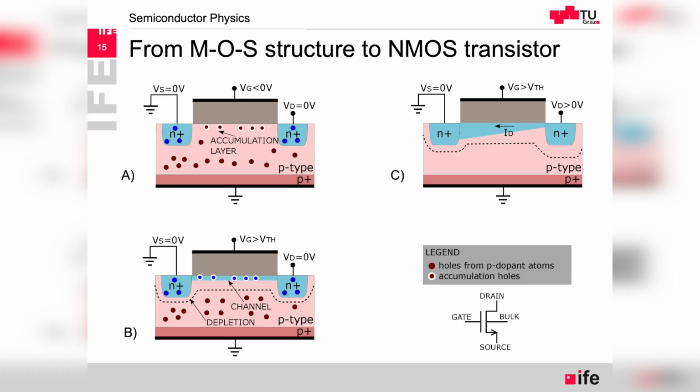And we can see here in picture A the accumulation condition where the transistor is switched off, and even if we apply voltage between drain and source, we see only some leakage current, which is related on one hand to traps under the gate because there is some discontinuity of the material of silicon, and then there is a silicon dioxide gate.